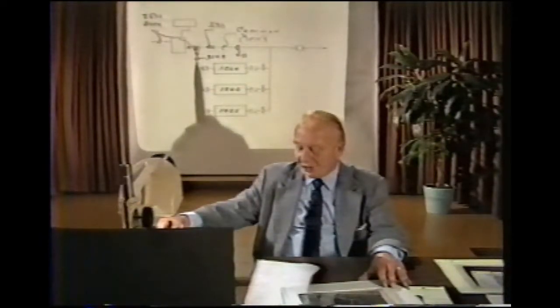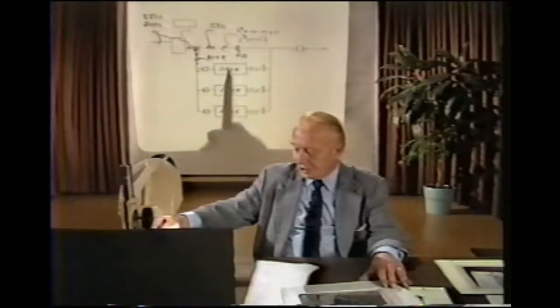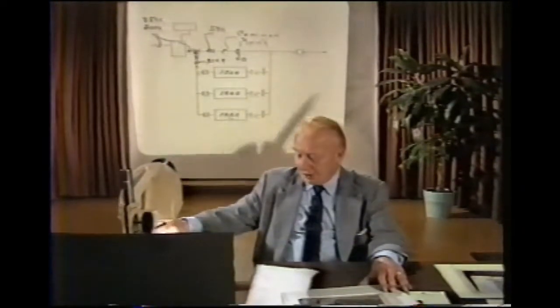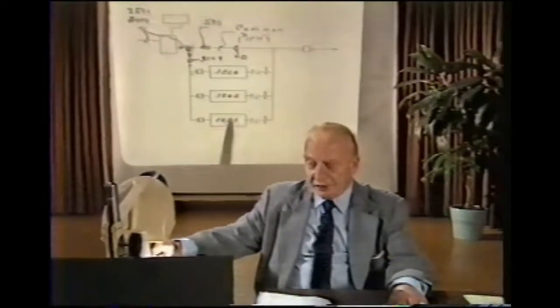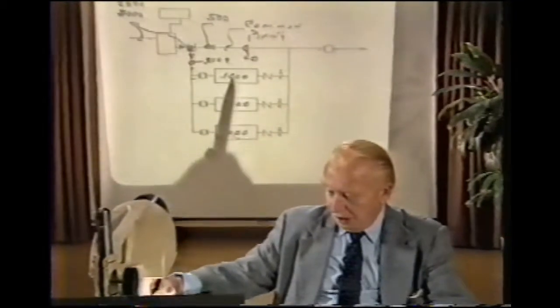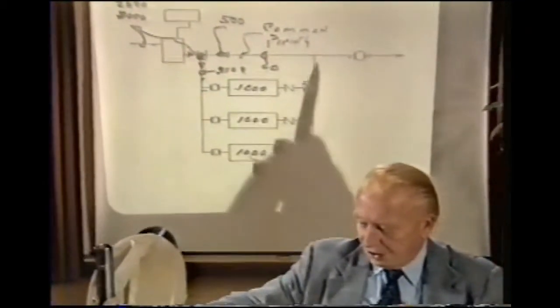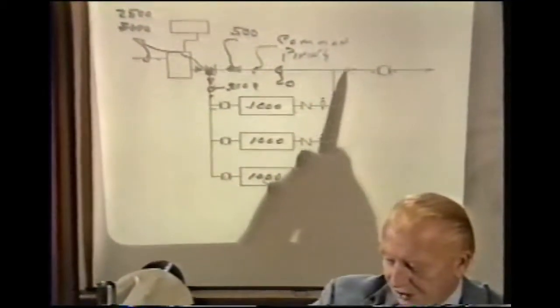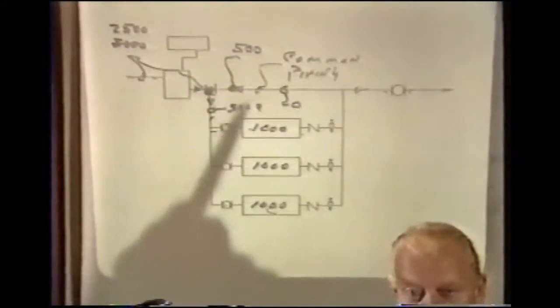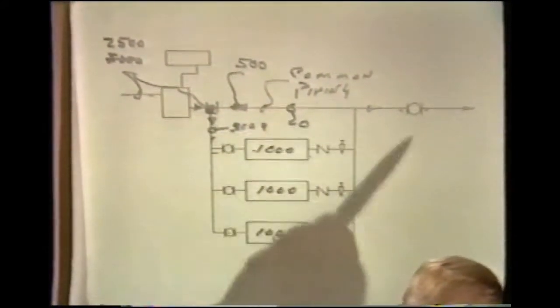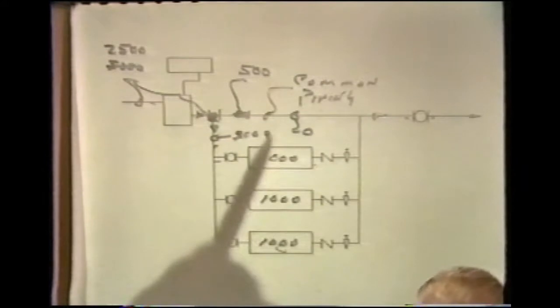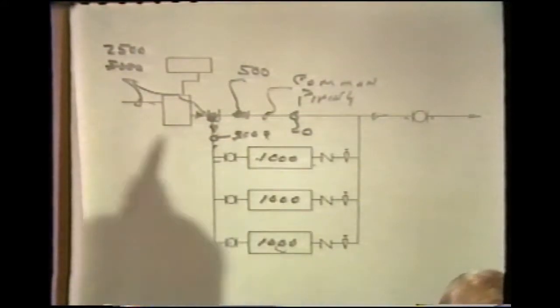This will then decrease the water temperature entering into the chillers, causing the chillers to deload equally and operate so as to still provide the necessary chilled water supply to the system, even though the flow rate has decreased in that system.